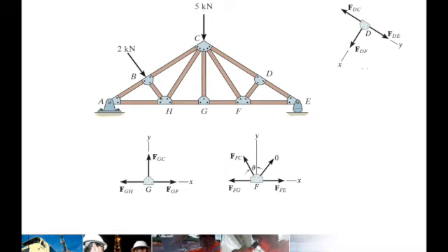So that is the purpose of your zero force member. If there is maybe a shock load or an unanticipated load that occurs in your design, it will compensate for that. Okay, so not because they are just zero force members you can omit them. No, they are there for stability.